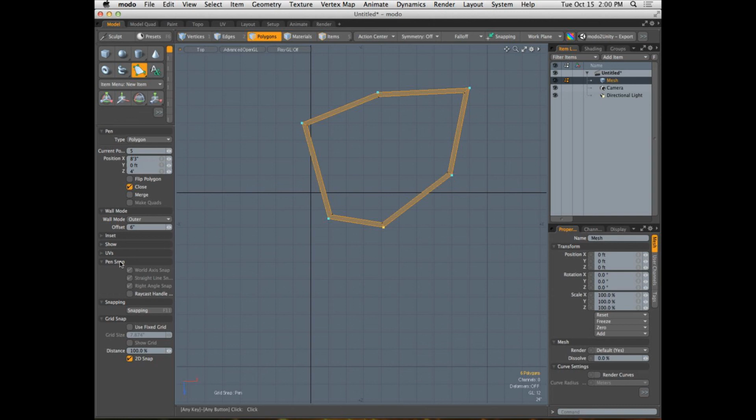How do I turn the snapping engine back on? I'm in the pen tool options. So keep cruising down that list. I'm not seeing pen snap. It might be cut off on your interface. Those little double arrows at the bottom of your screen will continue to expand and show the interface. Did you find it? Great, perfect. So how do I turn the snapping engine on? Hit the X key, snapping engine's on, boom,